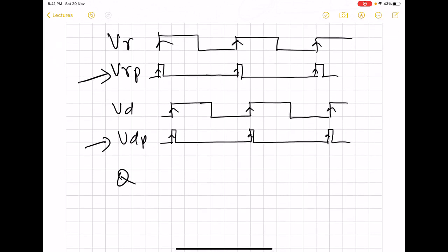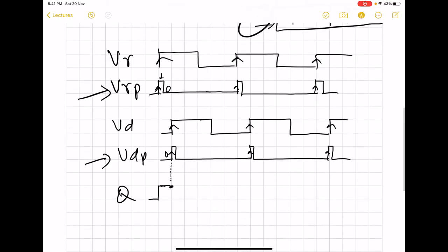So now here we see that when VR pulse becomes 1 for short duration, output will be changed to 1. And then it comes back to 0. So we now have 0, 0 condition. So here we see that we will have the same value, and this same value will continue till the rising edge or the pulse for VD comes. So when we have a pulse for VD, we have 1 here and 0 for the reference signal. So this will be brought back to 0.